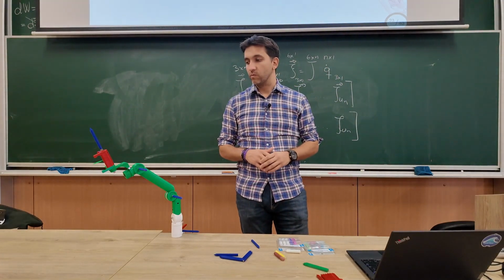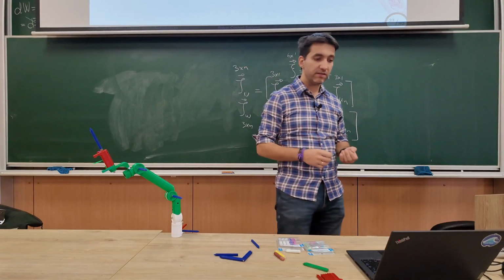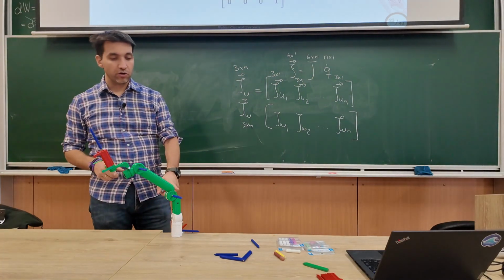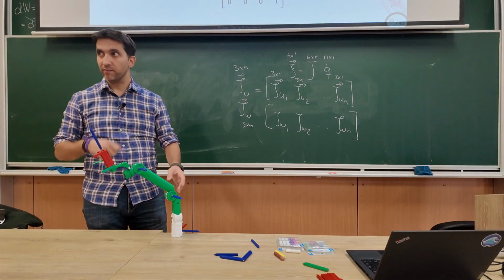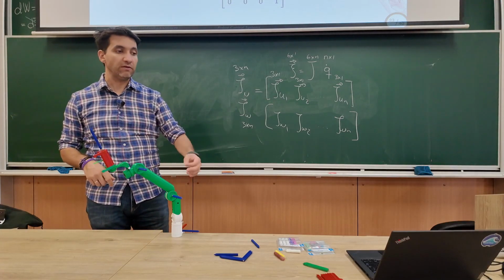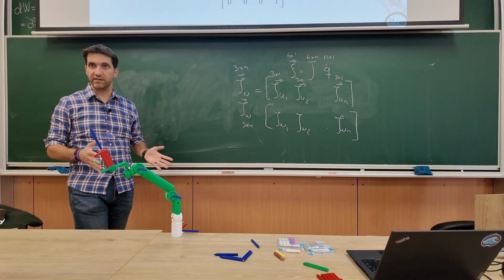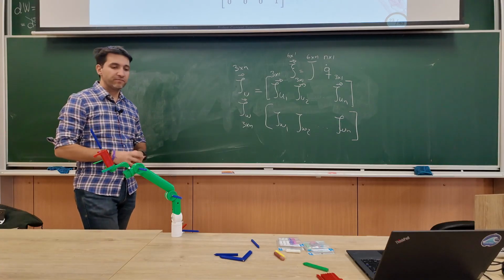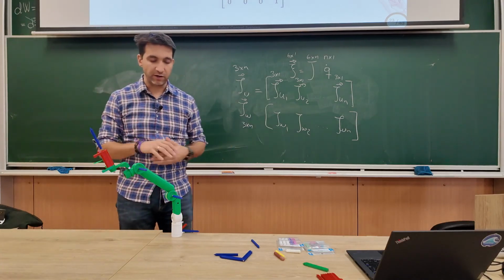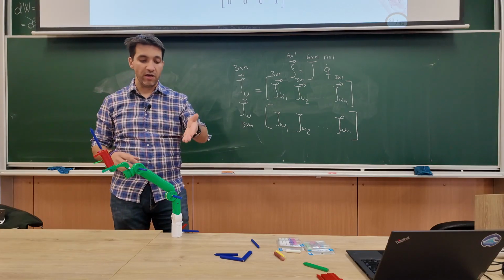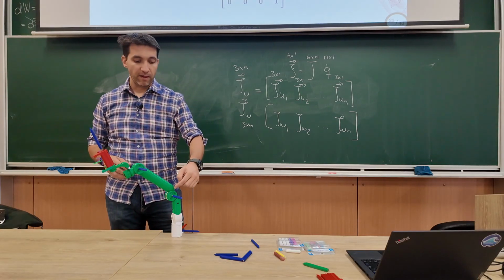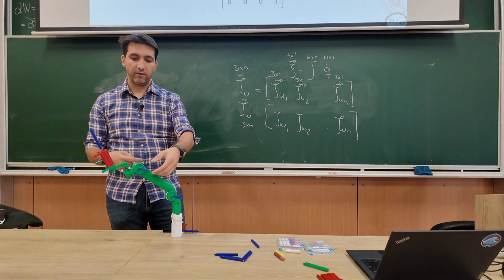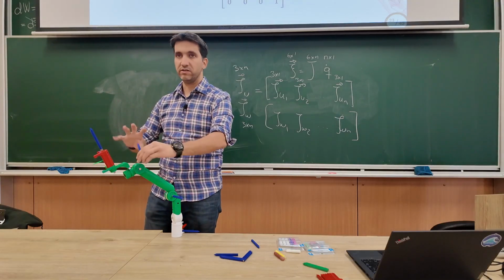So this Zi basically relates to what? To the orientation of the z-axis of the frame located at the joint, if we follow the Denavit-Hartenberg convention, right? That's the assumption, and we should follow it. Otherwise, we have to figure out which axis to take if we put the coordinate frame randomly. But if we follow the Denavit-Hartenberg convention, we know we place the z-axis of that frame aligned with the axis of rotation. We also ensure that we put it the right way. So if it's rotating positively, which direction, right?